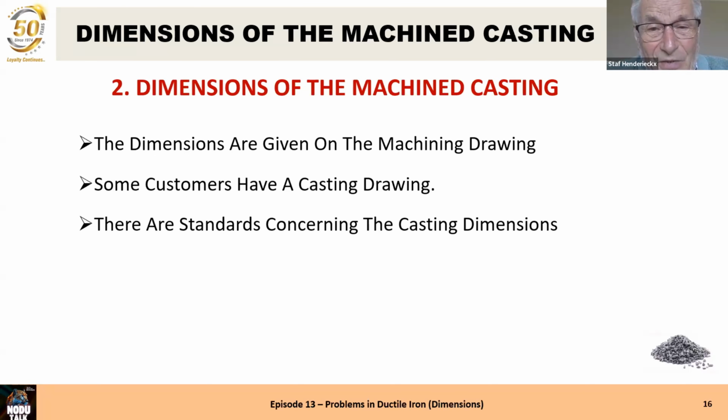And for the casting drawing, we have standards which can guide us for having the tolerances, but not on the machining drawing, because a machining drawing is for the machining shop and is not for the foundry. Please always try to get a casting drawing.